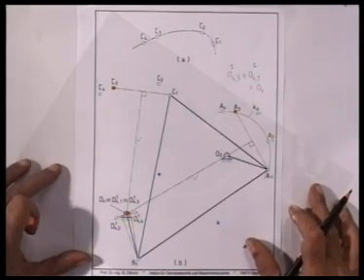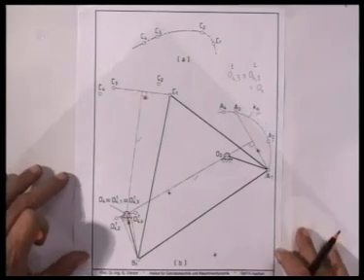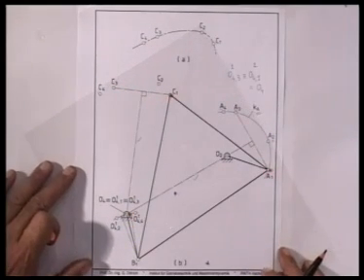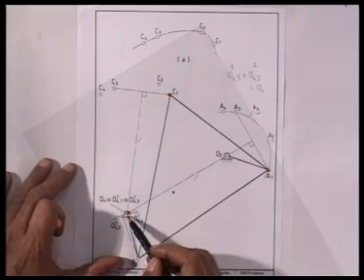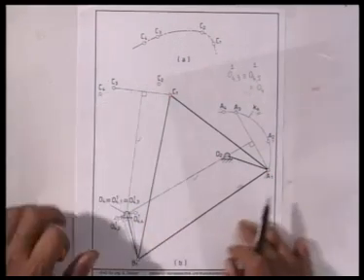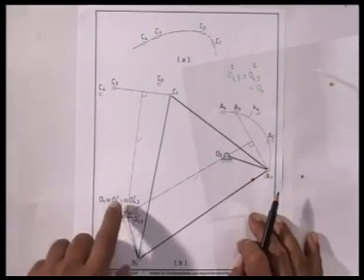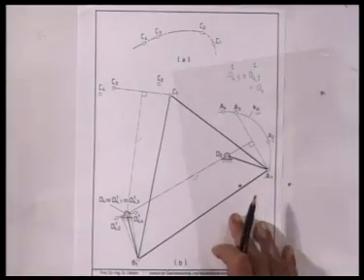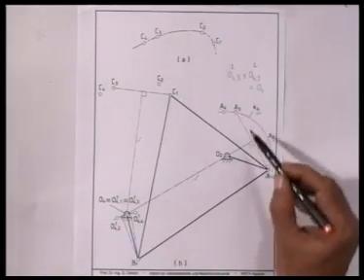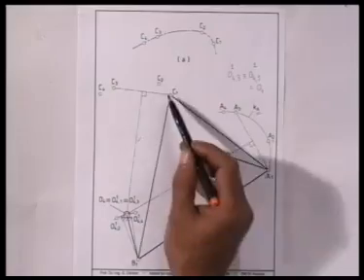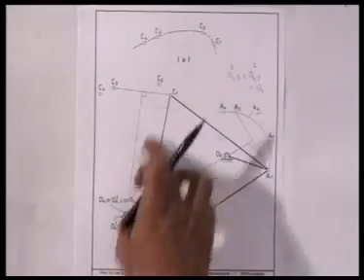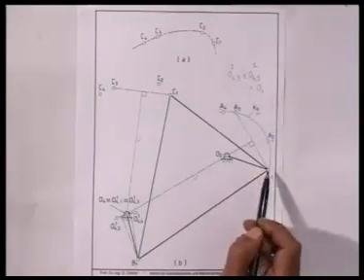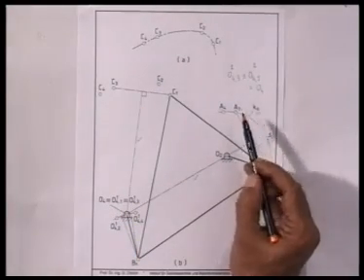If I invert it on the first position, that is A3 coincides with A1 and C3 coincides with C1, as we see the point O4 does not move. So this is also O4,3,1. It is the same point, O4 is O4,3,1. This is obvious because O4 has been located on the perpendicular bisector of A1, A3 and C1, C3. So the O4, A1, C1 triangle moves as a rigid triangle from the first to the third configuration.